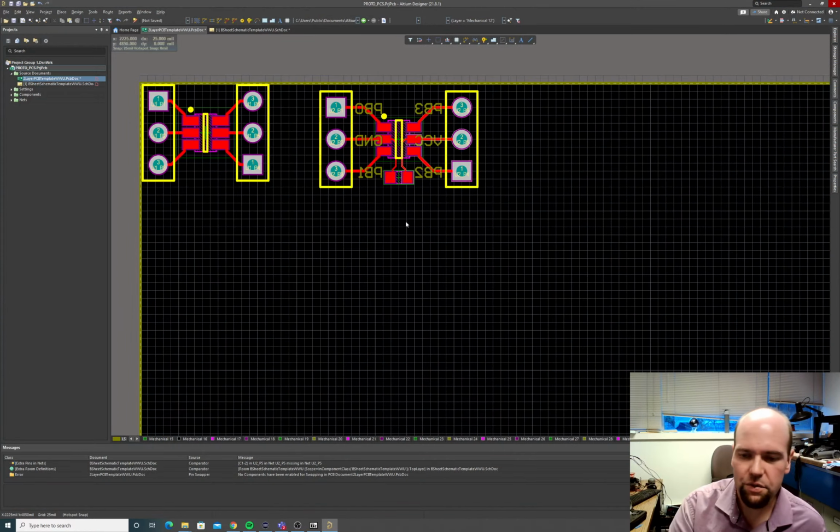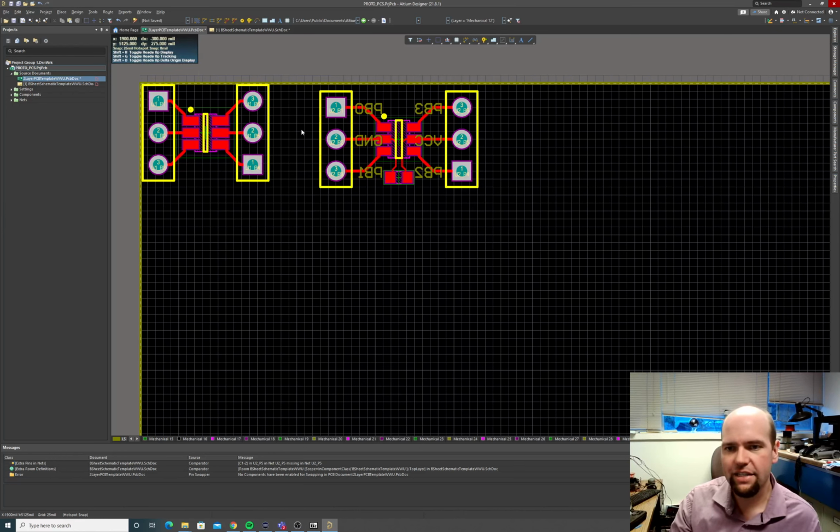We generally want to make sure we have a little bit of extra space beyond that. So one thing we can do, if this is the idea that we're going with, is leave 6 millimeters of space around all of these parts as we place them. This corner part doesn't necessarily matter so much. This part in the corner, it's fine in the corner, but we want to make sure that anything that's next to it has enough buffer that we're able to nibble these things out.